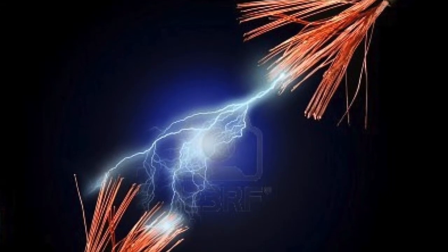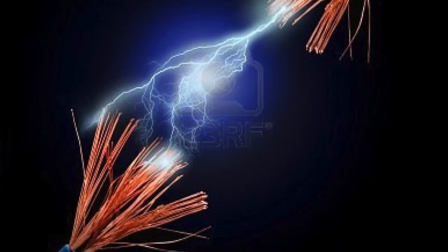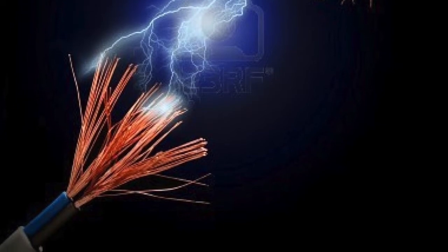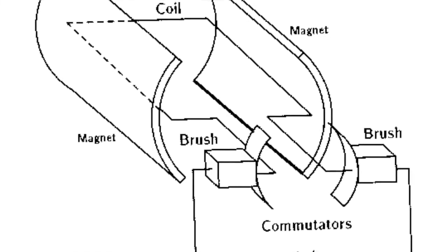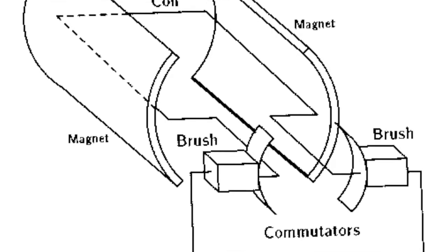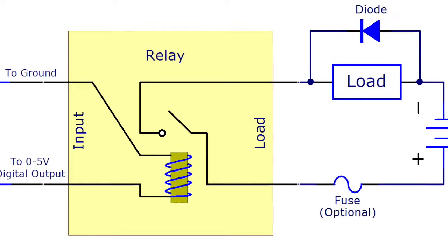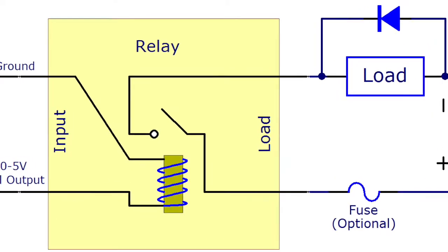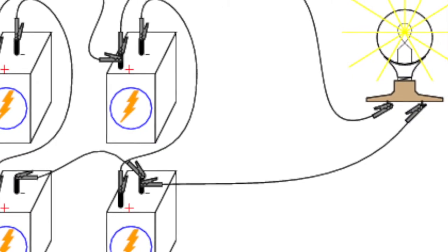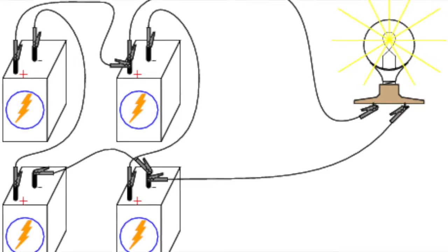What are the dangers of electricity and their causes? Indirect dangers. The storage and use of electricity is often associated with sparks, electrical or electrostatic discharges. For example, motors with brushes have short arcs between the brush tips and the moving rotor constantly during operation. Relays and switches open and close with a small arc between the contacts. Plugging in an appliance which is already turned on causes a small spark. Connecting a battery to a device which is turned on will also cause a small spark.